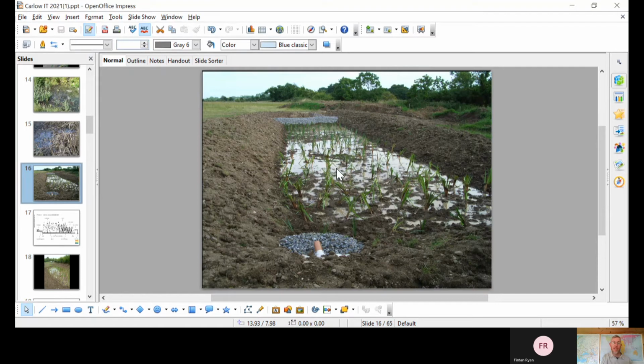One of the important reasons for the residence time is that if we have a 10-day retention time within our basin, it gives us time for uptake or removal and die-off of enteric bacteria. Enteric, as the name suggests, means inside. Those bacteria from inside our own gut are particularly fond of the temperature in the gut. As soon as they leave the body, they begin to die off. So a 10-day retention time will give you a good die-off of those bacteria before the percolation area.